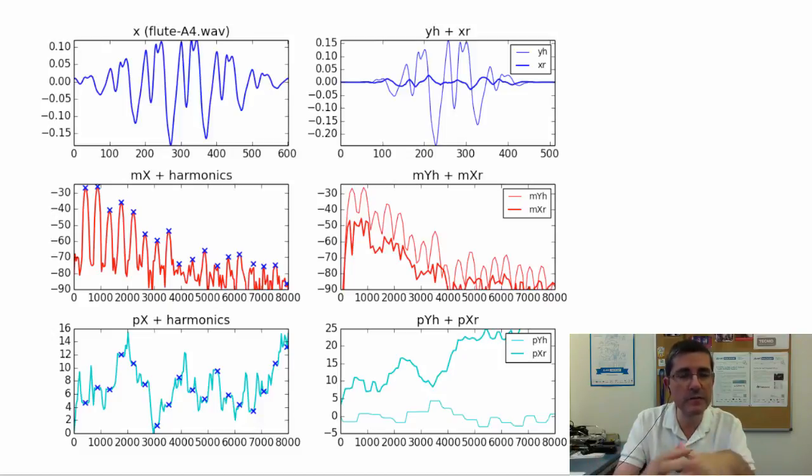This is a Blackman-Harris window used in the synthesis. So this is the synthesized spectrum, and then we have to subtract this spectrum from the original spectrum. Strictly speaking, we don't subtract it from the spectrum on the left, we subtract it from another generated spectrum that has the same parameters, so that we can subtract the two of the same size and the same window size.